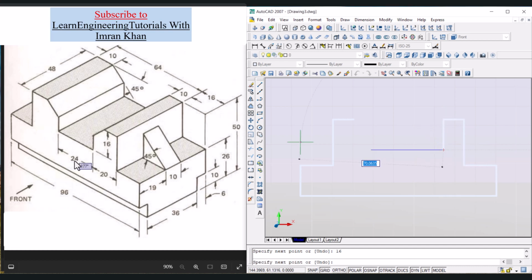And then because this length is 24 and this total length is 64 in this direction, we are left with 40 mm distance for this object and this object. 10 is already taken by this upper side, so we will be left with 10 more, which will be this inclined area. So in this direction write 10 and then write 24 and 10 again and close this object.